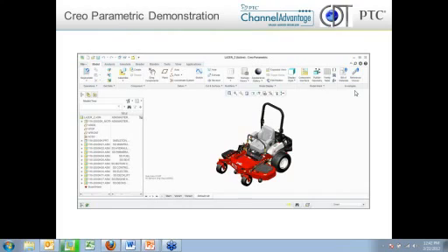So the advantages of an external Simplified Rep, again, would just be to speed up the regeneration times of an assembly. Since the parts collect their geometry info from skeletons, the objects are dependent on other objects to open and regen. So the skeleton is kind of its own feature. It's created like another part within the assembly. The other parts are based off of the skeleton more than the skeleton is based off of the parts that are there. I don't know if that answers your question or not.